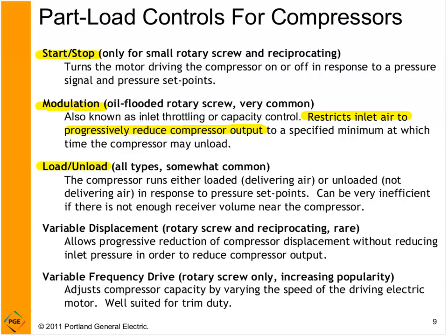But with load-unload, it does, and it's kind of like you're at a stop sign with your car. You have the transmission in neutral or the clutch in, which is hard on clutch components, but that's another subject. You're sitting there and the car is just idling. It's using some fuel, but nothing compared to when you're driving. So you're just kind of idling along, not doing any work. You're not going anywhere. The compressor's not putting out any air. It's just waiting for that low pressure set point to be reached.